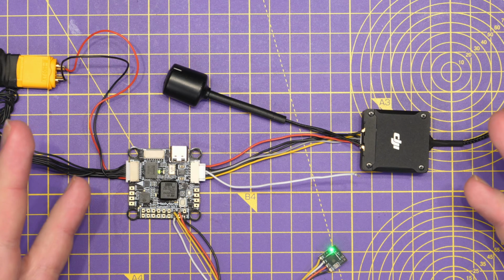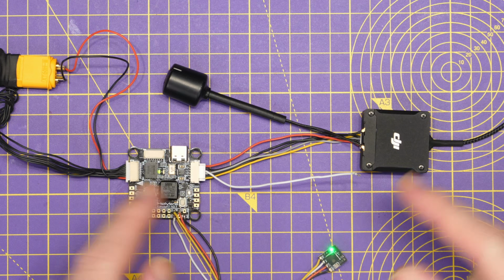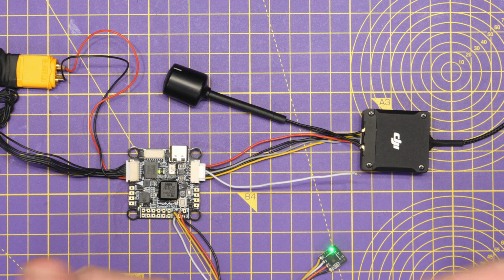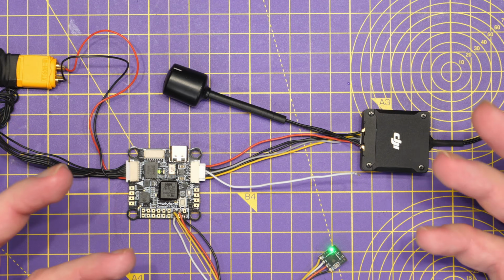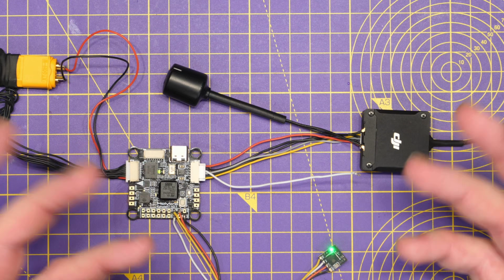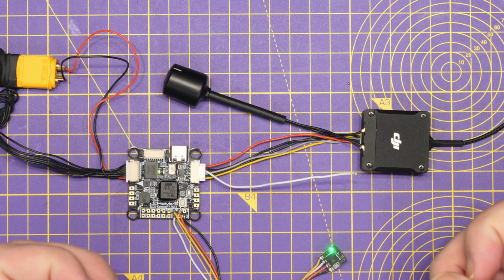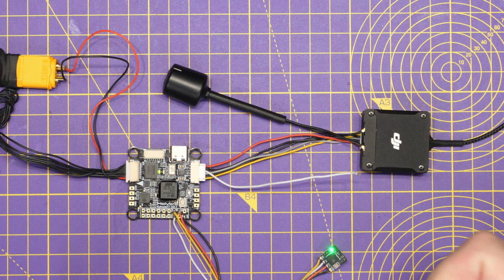Obviously, in this scenario, what you'd need to be doing is checking that these connections are correct, but then you would need to go back and start looking at Betaflight, because this is very much the same type of issue that you would get if your MSP configuration isn't correct in Betaflight itself. Now, if you're still having OSD issues after doing the setup, configuration, and you've checked the hardware, there are a few other things that you can check in Betaflight, and I'll just walk you through the manual configuration checks for them now.